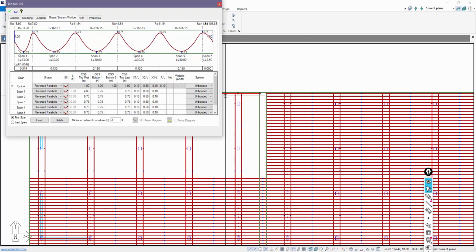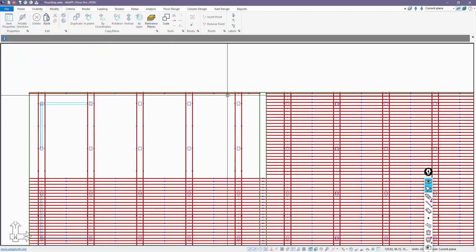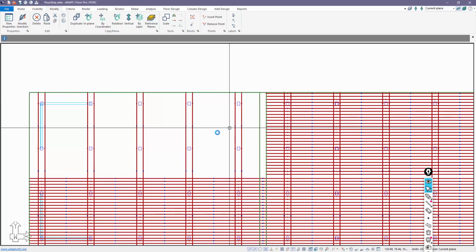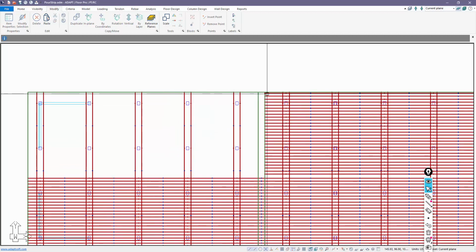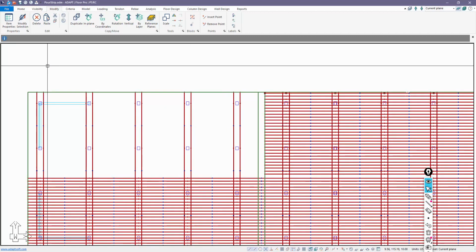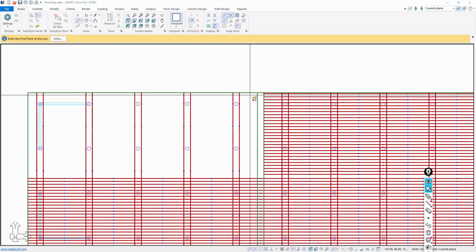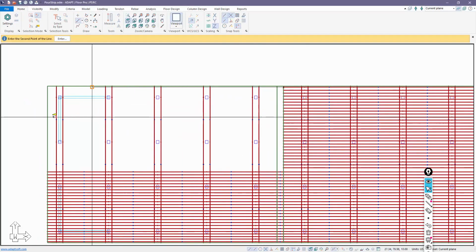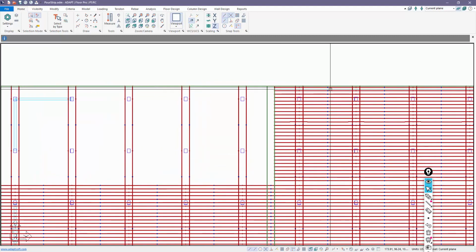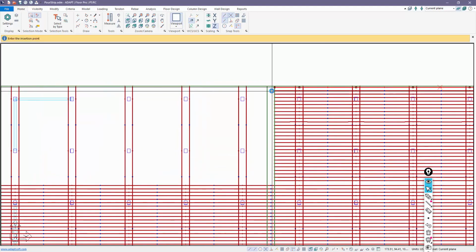Now notice when we mirror it, the mirror does not flip this image. So now we're kind of working from both directions, which can be confusing. So rather than mirror, what we recommend is really just to copy it over to this point. I deleted that line, and I shouldn't have deleted that. We're going to come back, create that construction line again, and I'll just use Control C, Control V.